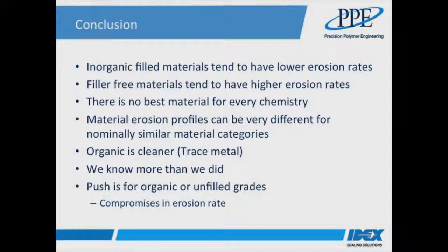Right now that means a compromise in lifetime, but based on our SEM analysis and on the one development material, not all unfilled grades are created equal. And of course I should mention that at the end of the day the choice of elastomer comes down to a number of factors, and many that we haven't actually discussed today, such as, for example, temperature capability and, depending on application, potentially also mechanical properties, etc.